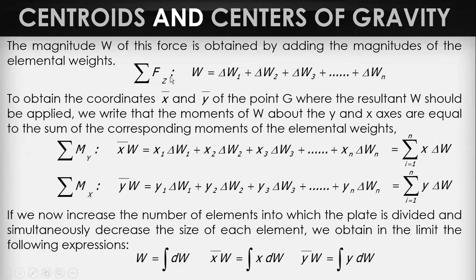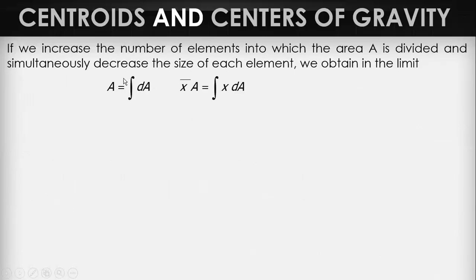So, this one, okay. If we replace this one, A will be equal to integral of dA, and then X bar A, integral of X dA, and then Y bar A, integral of Y dA. So if we use the method of integration, this will be the formula that we are going to use.